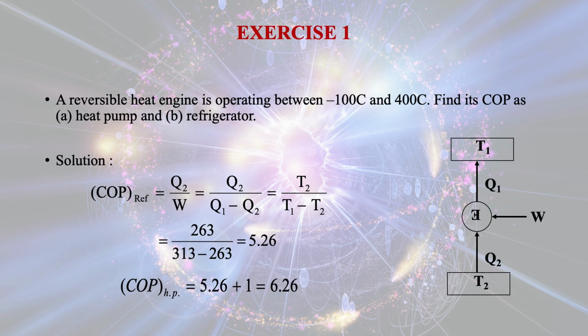Just put these values in the expression of COP of refrigerator. But dear students, please be careful while putting these values in the expression. Before that, we have to convert it in Kelvin scale.